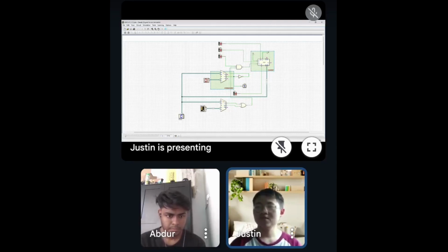circuit. To test the lift controller, clear pin needs to be disabled, which is clear pin is 1, and enable pin should be enabled, in which the enable pin is 1. Keep the load set at 0, since when activated, counter or register won't count, but will load a value presented on its data inputs. Set the enable terminal to 1, to allow the counter to perform its normal function when enable input is active. This provides greater control over operation of controller.